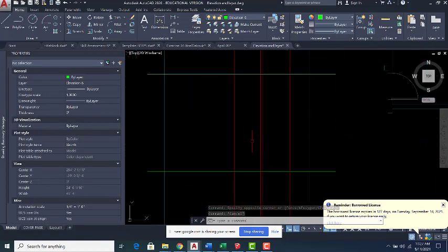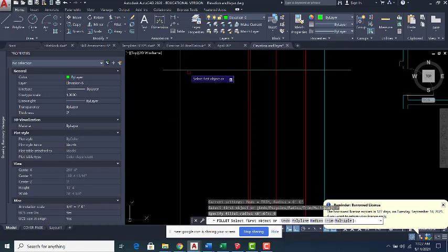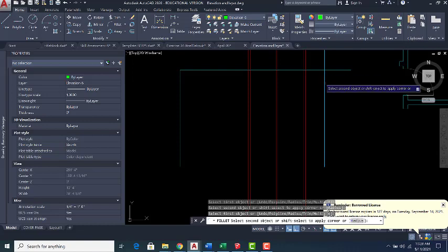So now, even if I'm here, even if I don't see the plan, I know what's happening. These are wall, ceiling, wall, floor. These are my windows. So what I would do here, sometimes I use trim, sometimes I use fillet. So here I use fillet R0, and because I have more than one, I would go immediately with multiple, and I just go around and get rid of those extra pieces. Now I have my room completely.